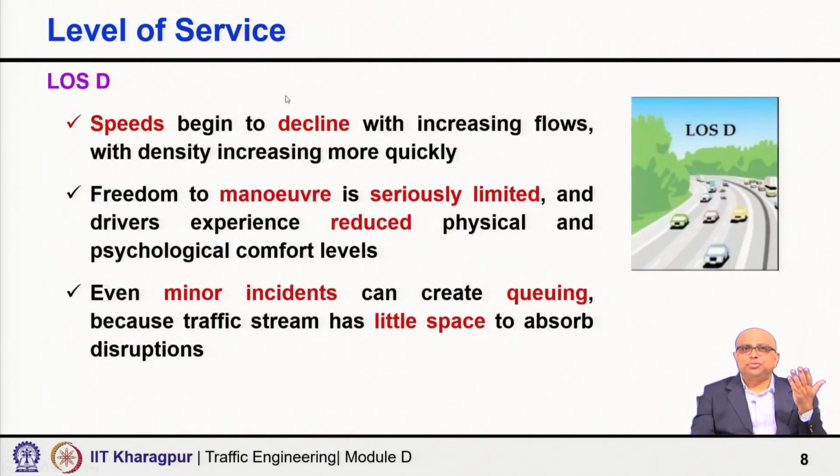LOS D, speed begins to decline now with increasing flows. So, we have gone to the other side, where the speed drop starts happening very fast, with density increasing more quickly because there is a speed drop. Earlier, with the increase in the flow rate, the density was increasing, but now the density will increase at a faster rate. Freedom to maneuver is seriously limited and drivers experience reduced physical and psychological comfort levels.